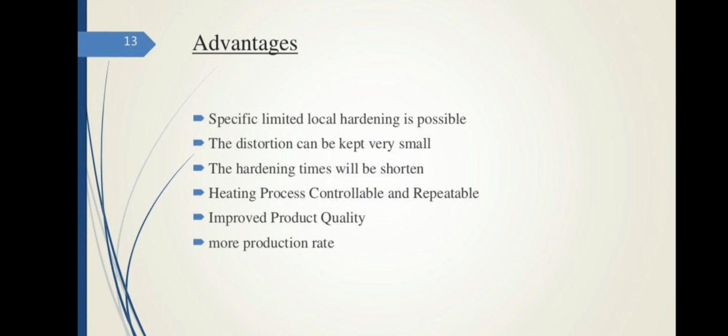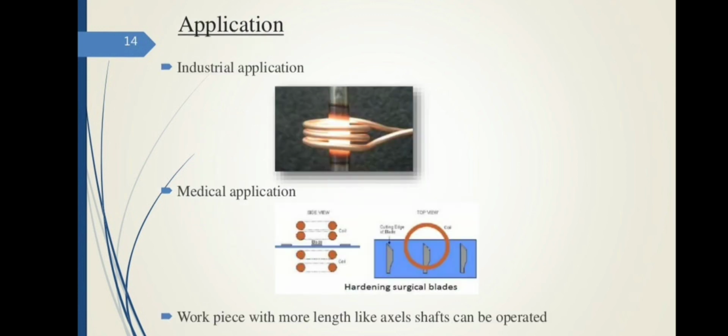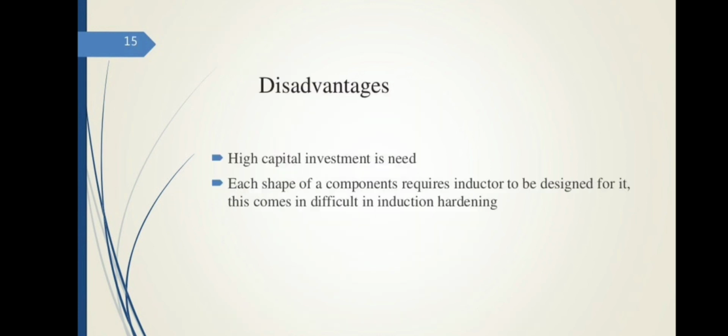The major advantages of this induction process are that specific limited local hardening is possible, distortion can be kept very small, hardening times are shortened, the heating process is controllable and repeatable, and there is improved product quality and even higher production rate. It has numerous applications in industrial and medical fields, and even workpieces of great length like axle shafts can be processed.